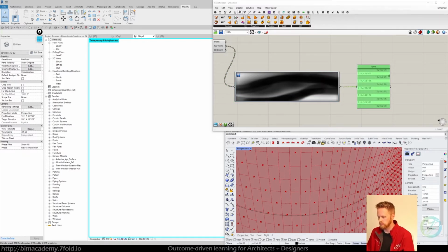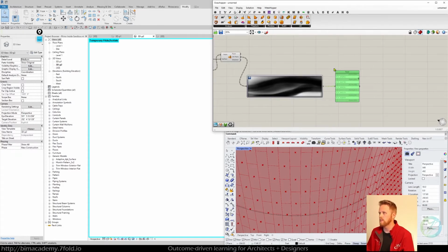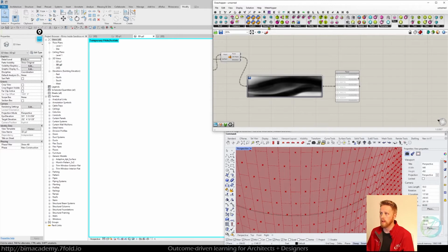All right. Eventually, we're going to be landing at the Revit adaptive component Grasshopper component. That's a mouthful. To find that, we can do add or build, and say add component adaptive.